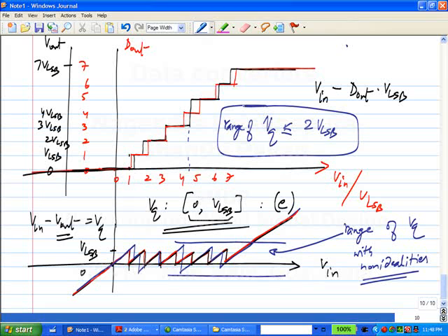Okay. So, inherently in the quantization process, there is some error, and I will allow myself some more error so that I am able to design it at all. And I will allow myself exactly the same error that is inherent in the quantization process. Okay. So, this is the typical definition, but this is not universally true. Maybe when you actually design an A2D for a specific application, you may be able to tolerate more, or you may have to tolerate less. Okay. But this is a number. In absence of any further information, you can use this to be the number. Okay.